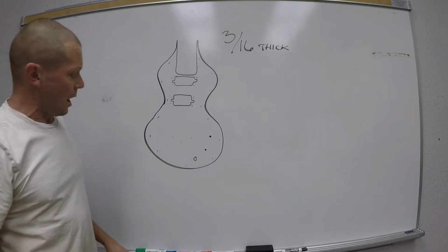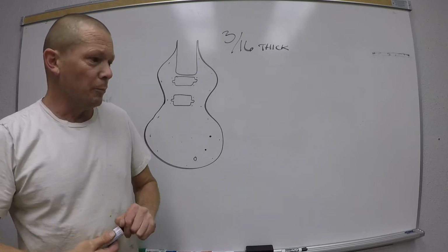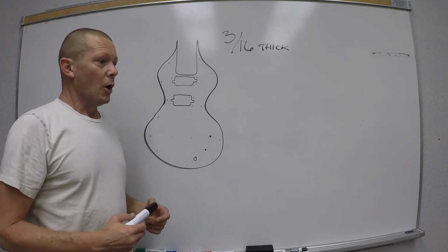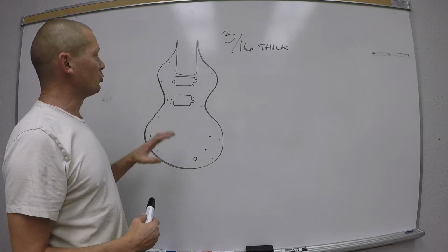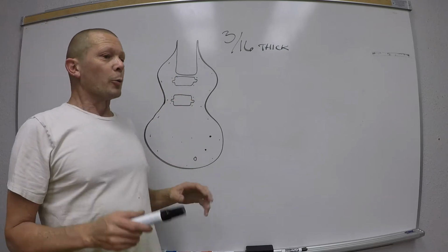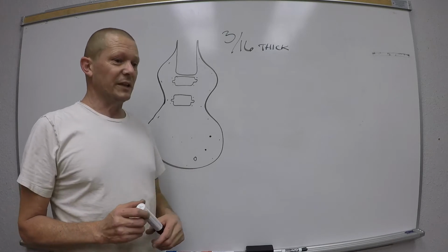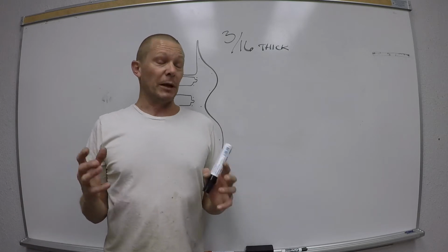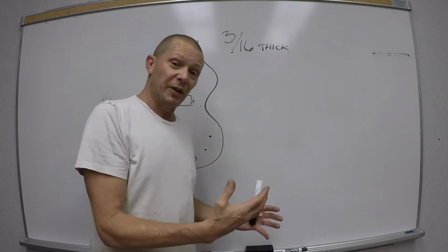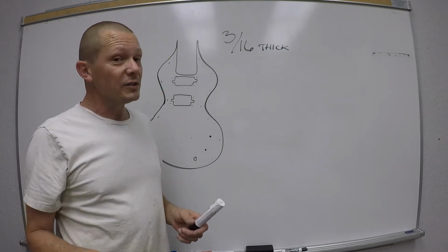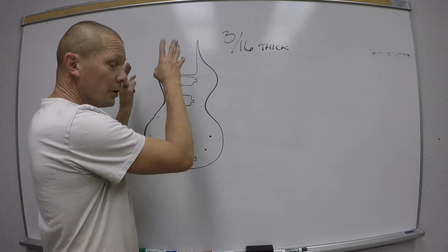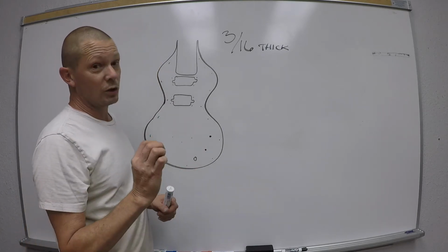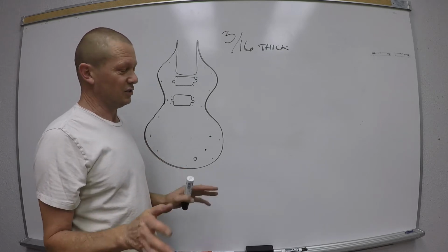So I've touched on it a few times before. When we make parts, whether they're CNC'd or they are made manually, if at all possible, we always want to drill the holes first, okay? The reason for that is because if you have holes in something, typically something bolts to it, or it bolts to something, and sometimes, not always, some of the other operations in that part aren't as critical as those holes.